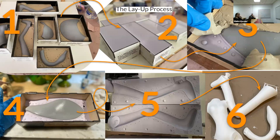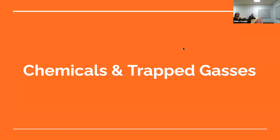So you're finding a seam. We've all had some crappy plastic toy where you could clearly see the seam. This is planning for where that seam belongs, trying to avoid seeing the seam by doing it this way. It gets you a much cleaner seam line where you're not going to have a ton of flashing. Like if you're making dice, you want your seam line to be on the edges, not in the middle of a face on the dice. Taking the time to do it this way influences the amount of cleanup it takes per piece a lot. So if you're making a bunch of stuff, you take the time to do it this way if you want to avoid having to sand for the rest of your life.